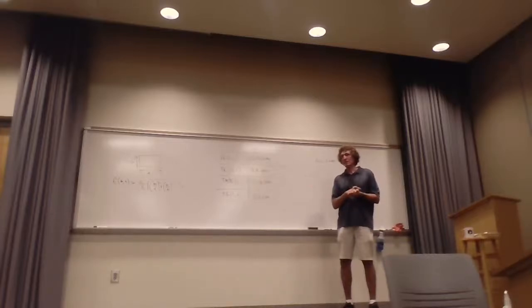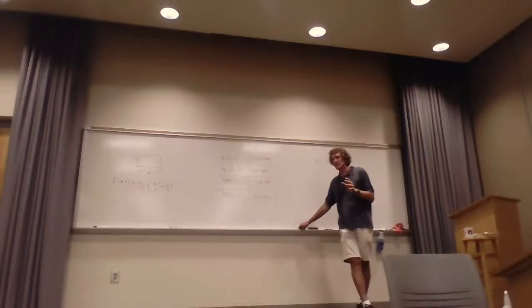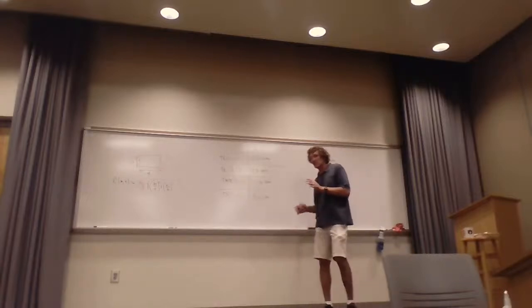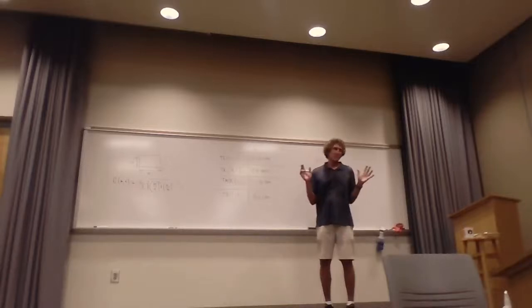Now, I just want to say this, in case you get into some situation when you're in grad school or something. When a waveguide is driven below cutoff, there is a theoretical impedance. I just want you to know that. The impedance itself is something we don't even touch in this course because it has to do with what's called an evanescent mode, a non-propagating mode. Let me just mention this for completeness. I don't know where that term comes from either, so you can look it up.